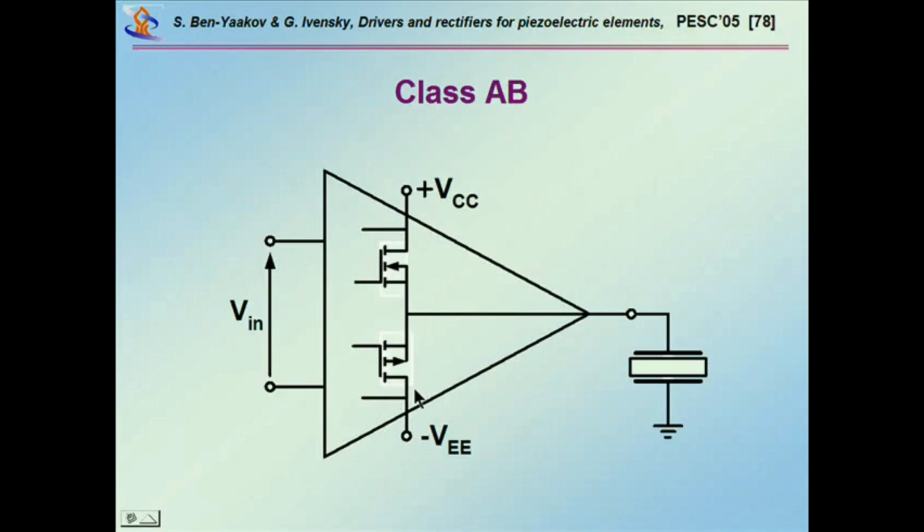Another problem, which is a little bit off what we are talking about, but let me just point it out, there is a problem of stabilizing these systems dynamically, because they are highly capacitive, so you have an extra phase shift, a lag phase shift, and then when you take a feedback to the input to get good tracking, you may run into a problem of low phase margin and therefore oscillation.